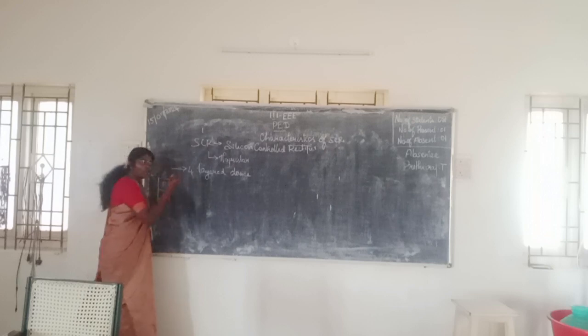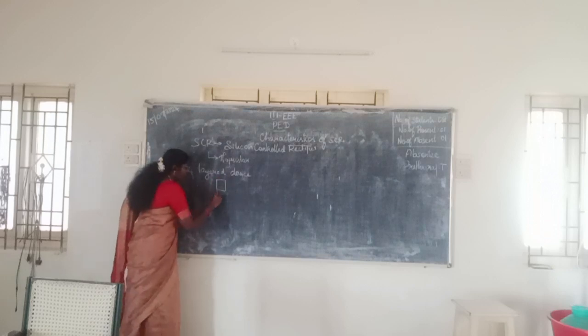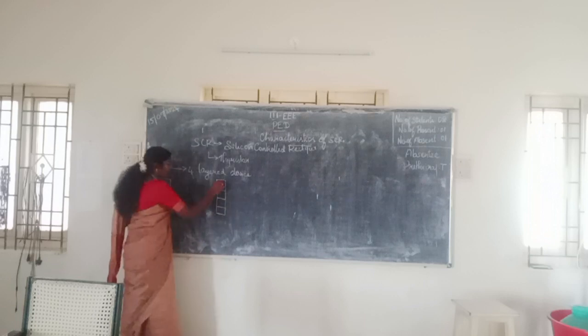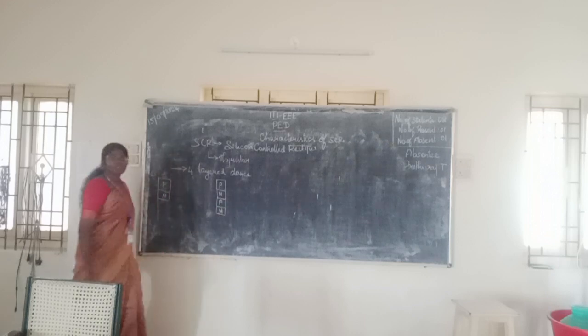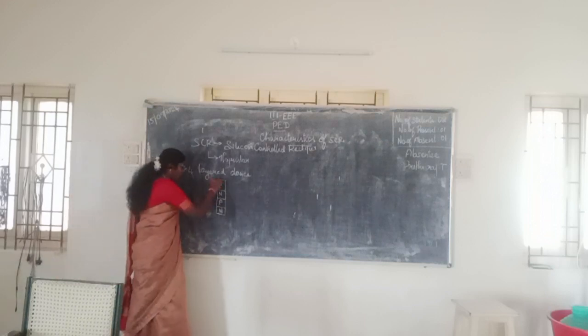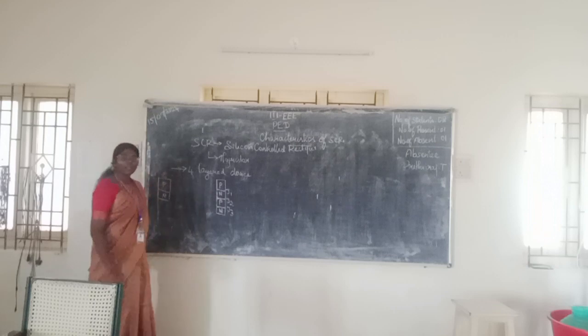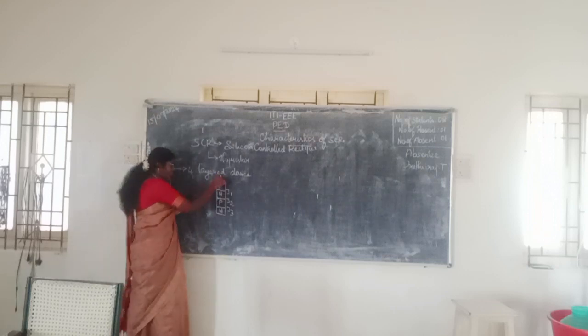Here one more P type and N type is going to be there, like P type, again N type, again P type, again N type, with these PN junctions. So 4-layered means how many junctions will be there? J1, J2, J3: 3 junctions.